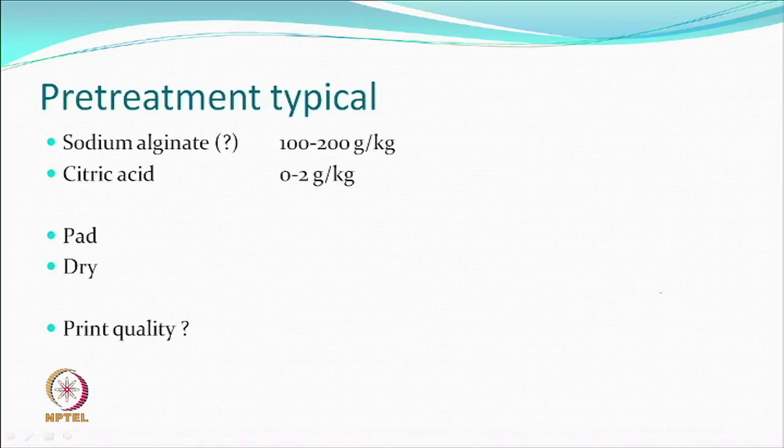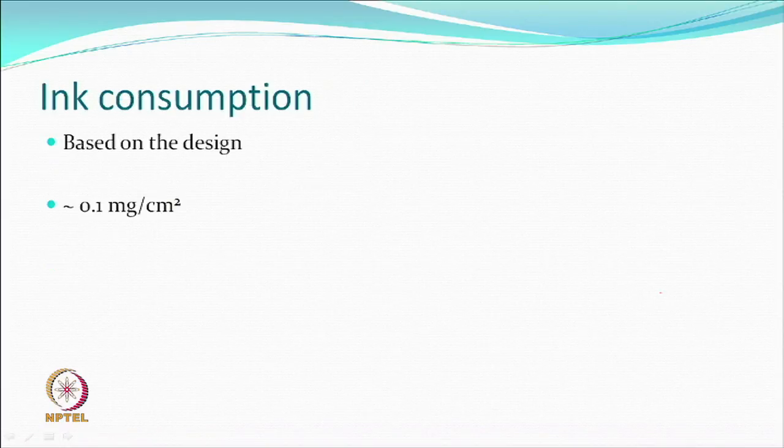So, after this you pad dry, and then we hope for the best that print quality is going to be taken care of. The ink that is consumed obviously depends on the design, whether you are covering 100% or 30%, 40%, but generally consumption is not very high. We hope that it is close to 0.1 milligram per centimeter square, which is reasonable as far as the costing is concerned.